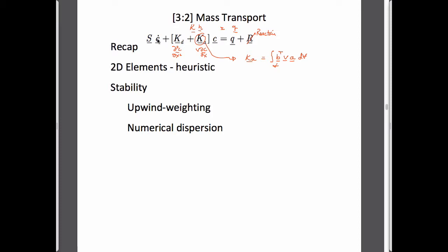So you can look at flow of the carrier fluid, typically water, with a concentration or a mass loading attached to it. If you prescribe that the velocity exits the element, then what it will do is it will basically strain the carrier component on the inside, and it won't leave. And so it won't allow it to actually go across that boundary. So we have to put a convective boundary condition to that. And so we'll talk a little bit about that today.